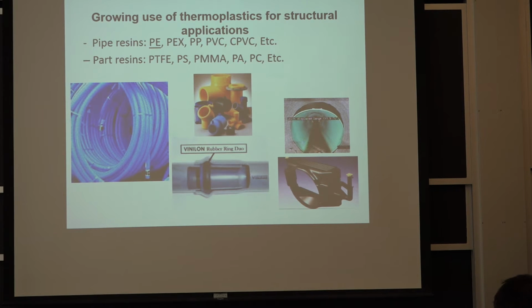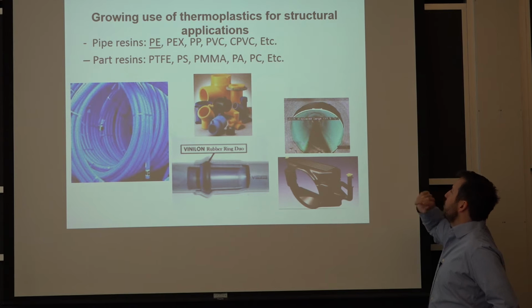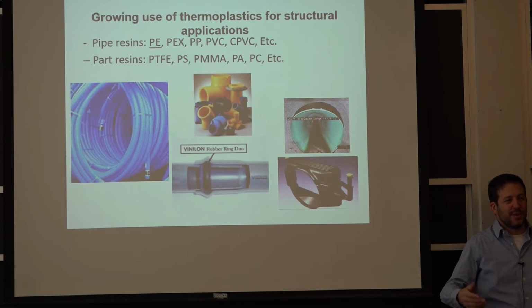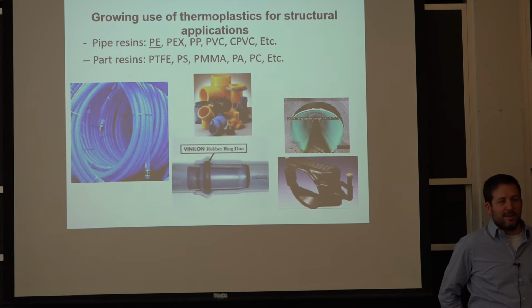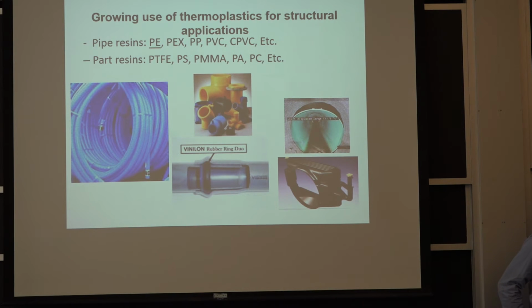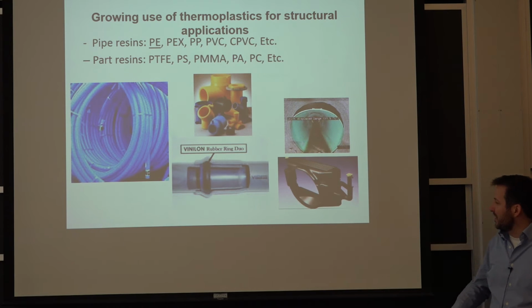You can use also the plastics for underground pipes. This is just for drainage. And you can see the issue, it's not round anymore because it's so soft that over time it's going to sag. So just the effect of the ground weight on the pipe is turning it into an oval. Eventually it can even collapse. So that's not very helpful and productive in a lot of cases. Here, this is just kind of a shield for the fan of a radiator in cars.